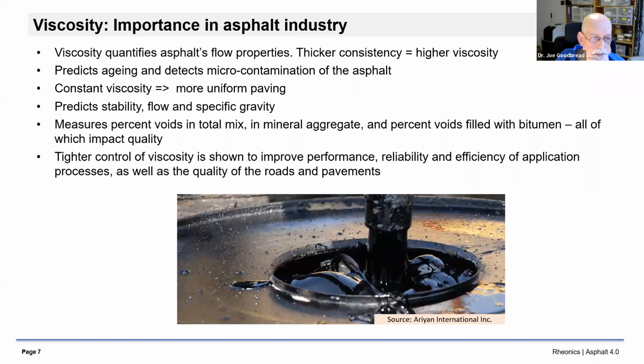Viscosity essentially is a measure of how fast a liquid flows under stress, whether that stress comes from gravity or from pumping or stirring or spreading. The higher the viscosity, the thicker the fluid, and the more slowly it flows under stress.